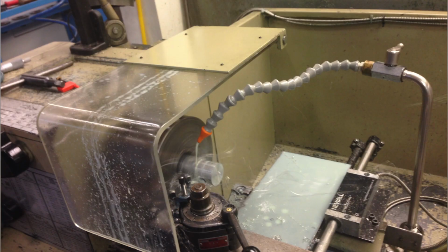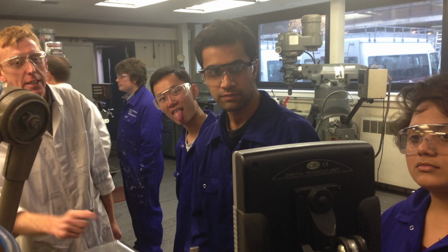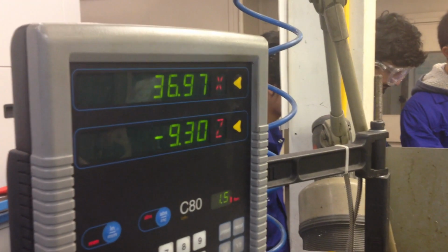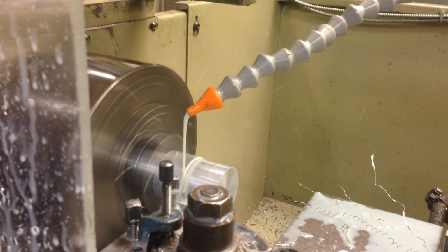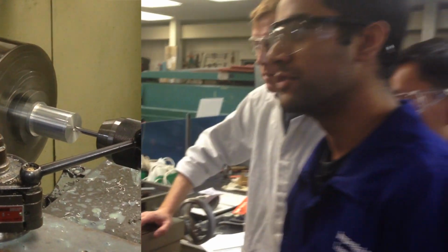I'll tell you how. First, we started off with a cylindrical block of aluminium. We went to the centre lathe and faced it off first. Next was to use the centre lathe again to cut the aluminium down to the correct length and the correct diameter for our hub. Then we used a tailstock to bore the 8mm hole for the shaft the hub would sit on. Next we went to the milling machine.